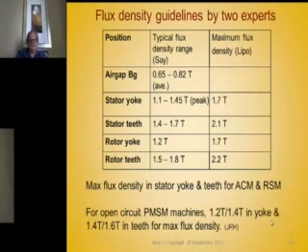Say recommended, in induction machines, an average air gap flux density of 0.65 to 0.82 Tesla. Lipo didn't provide that in the same reference, but I think it's safe to assume he was using the same kind of numbers.